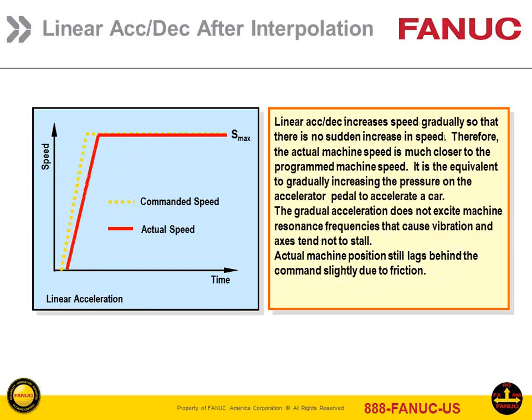Okay, so you'll need linear Acc and Dec after interpolation. What this does is help you gradually accelerate the axes, and it will help it start up gradually. The actual machine position might not be up to the actual speed that you want, but it'll be okay.